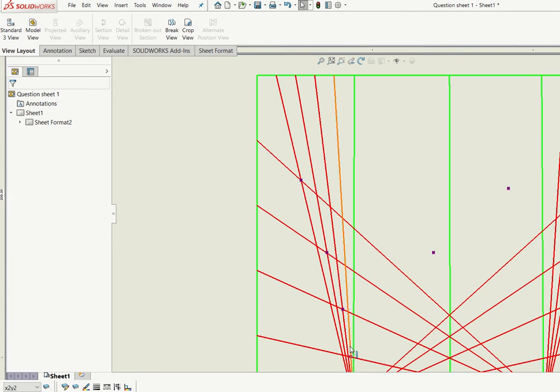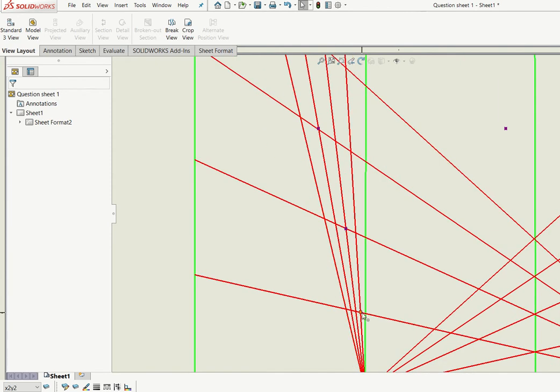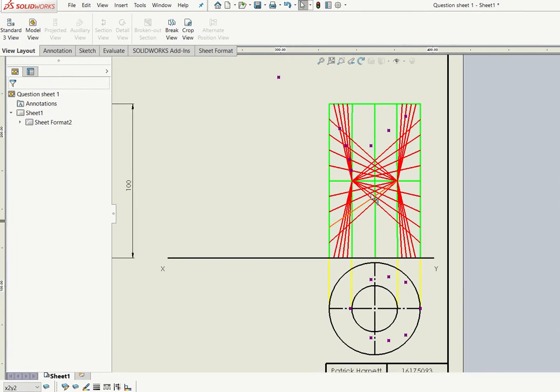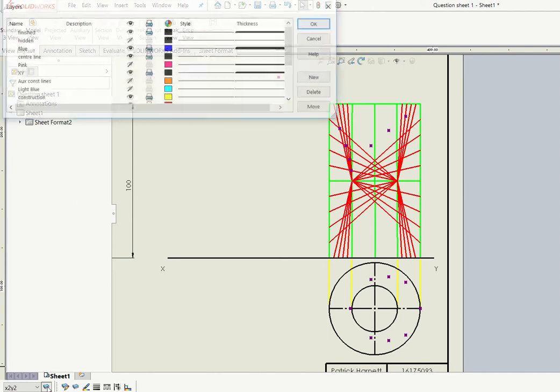And the same with line 4 and line 4 intersect to give us this point here. So once we have these points found, we can draw one section of our hyperboloid of revolution. Now this process is going to be the exact same for each rectangle in this construction, so you can just follow the same process the whole way around. These will give you points in each rectangle, and ultimately you'll be able to draw your hyperboloid of revolution.